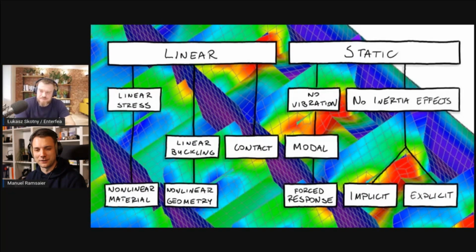It's different because it's more like a modal simulation where you find perturbations of your super esoteric matrix, really. Because when you see the outcome on a screen, the deformations make very little sense. The stresses make no sense at all. You cannot use the stress real values. Outcome is the shape, more or less. And then this magical multiplier. And this can catch people off guard because they will be trying to assess the values they get from this analysis. That's a pointless exercise.